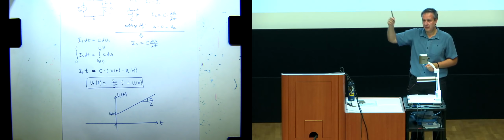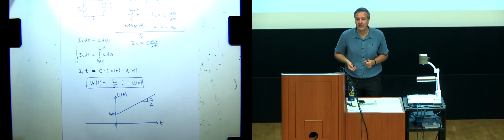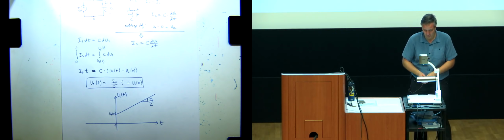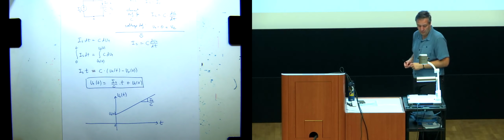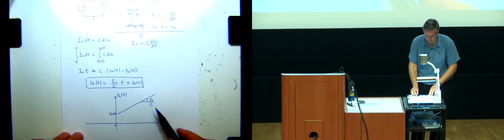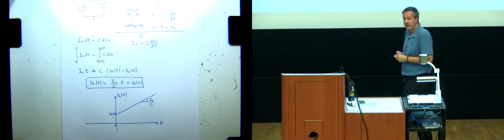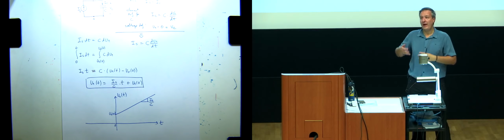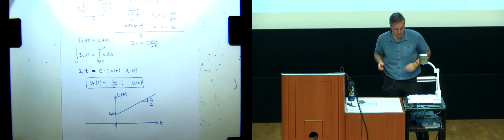the more rapidly I'm going to be charging up this capacitance, right? Because the current is proportional to the gradient of voltage, right? So the larger the current is, the larger my gradient of voltage will be. So the more rapidly I'll be charging up. And it's also C, the smaller the C is, the larger the voltage gradient will be as well, right? Or I'll be more rapidly charging that bucket, right, if the bucket is small.